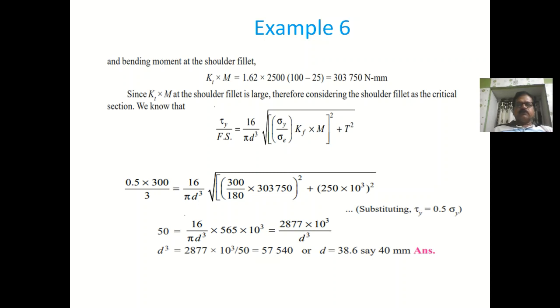And then the stress concentration: when the member has any surface irregularities like holes, notches, keyways, etc., they cause stress concentration. In order to reduce the stress concentration, we put additional holes or slots to make it uniform.